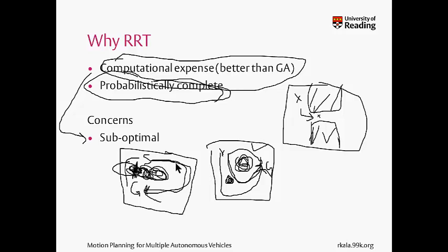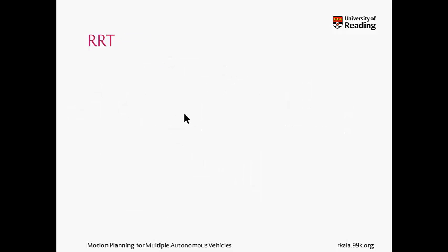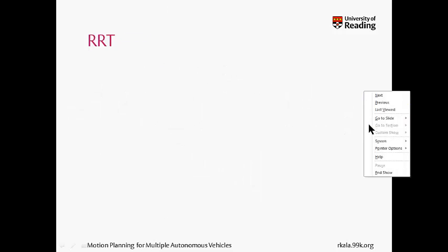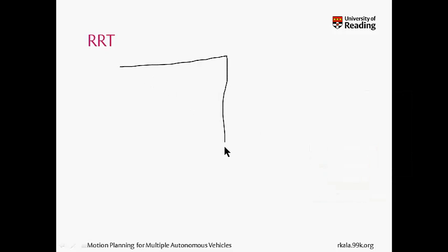And they are locally optimal, which means this path or a slightly longer path or slightly tilted path, RRT can generate anything. So the problem is that they are suboptimal in general. If this much suboptimality is okay, then it should be okay to use such algorithms, but if clear optimality is needed, then these are not the algorithms of choice. So we'll take a quick in-depth look at what RRTs are and how they function.